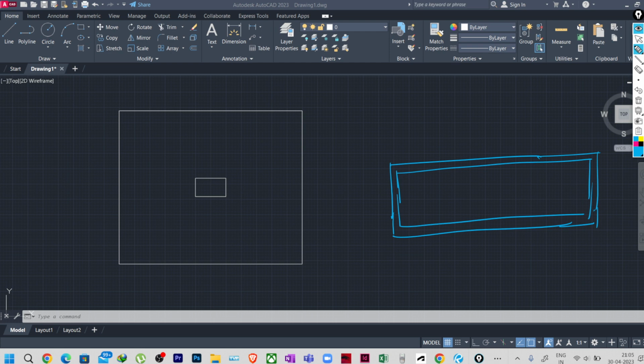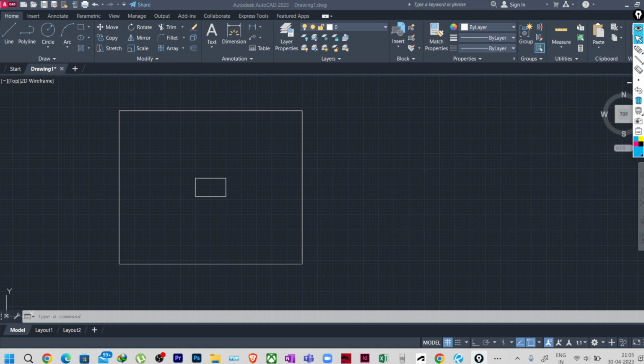Now this top and bottom reinforcement, obviously if there is no uplift, you will be providing a minimum reinforcement here, and this will be coming due to the moment that you are getting. Fine. And then obviously there will be some cross-sectional reinforcement also. So now this top and bottom reinforcement, let us show you how you can provide this. Let us begin with the bottom reinforcement.